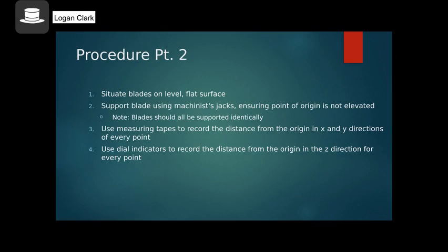For the next part of our procedure, we situated the blades on a flat, level surface. We made sure to support the blade using machinist jacks, ensuring the point of origin was not elevated. All blades were supported in the same exact manner to ensure the best repeatability in our experiment. Using measuring tapes, we recorded the distance from the origin in the x and y directions to every point. Next, we used dial indicators to record the distance from the origin in the z direction for every point.